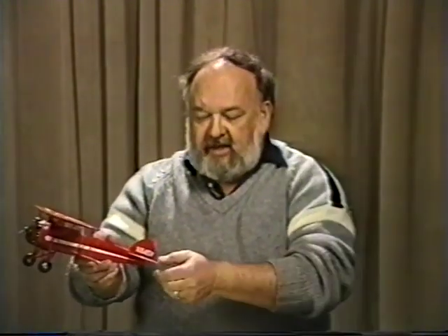Now, if you hit a gust or something like that, the ailerons won't move. They'll stay right there. They're locked into position. So roll stability is the same whether the stick is fixed or whether the stick is free to move. But the elevator and the rudder are different. If you're flying along and you hit a gust of air, the elevator will tend to float with whichever way the gust goes. So you can see that if you were holding the stick and locked onto it real tight when you hit a gust of air, that's the same as having more tail area. So therefore stick-fixed stability is higher than stick-free stability.